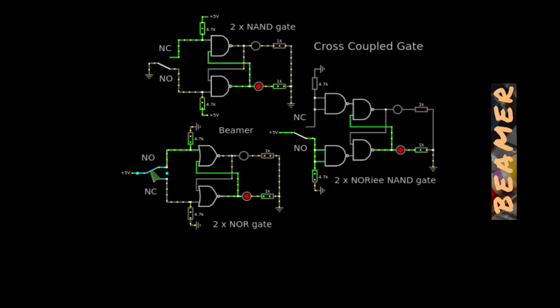And I finally move on to what I called here a 2 times NOR-by-NAND gate. It's worth bearing in mind when you're designing with discrete logic like this, it's good to have the truth table of the logic that you desire in your head. The actual implementation of the logic can be a varied number of gates. In other words, providing that the logic is true, it doesn't really matter what gates you use.